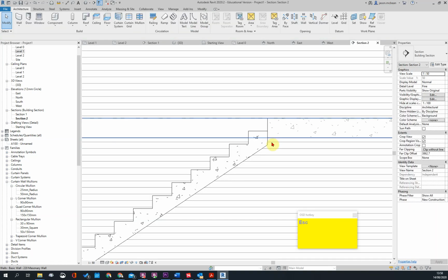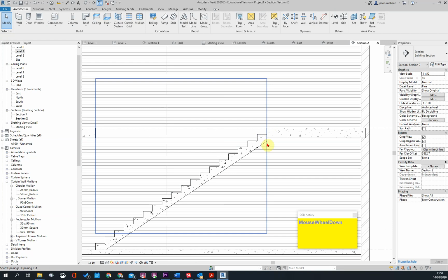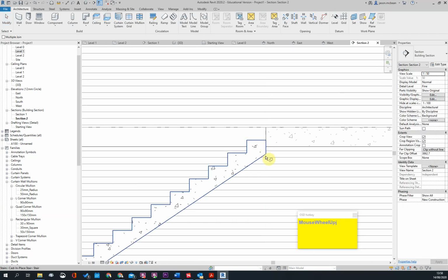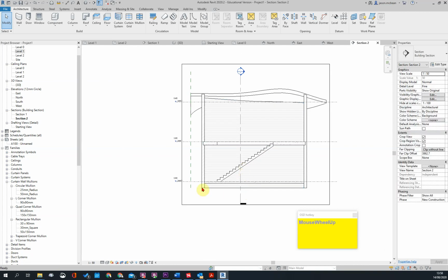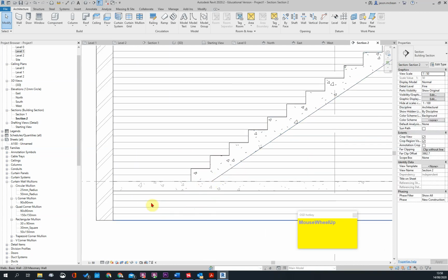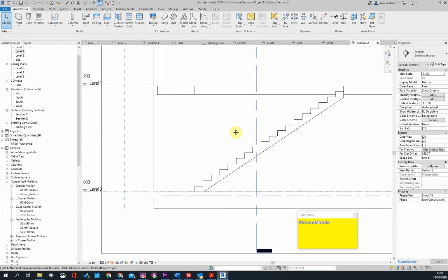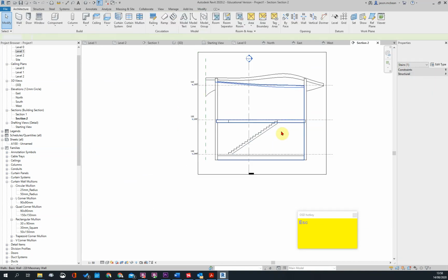And you want it to stop short. You use a filled region to do this connection. They never join. So a staircase will never join to a slab and make a neat connection. They're two separate objects, but in essence, here you're going to have to use some drafting elements to show how this joins with the floor, for example. But here you've got your stair in essence.